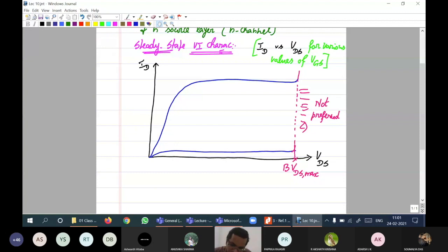Obviously, the gate source voltage values are essential. Now, the first value is going to be VGS threshold. Below that, the MOSFET is going to be under cutoff mode. Therefore, I will name this VGS threshold, VGS TH. And as I was mentioning, this is cutoff.